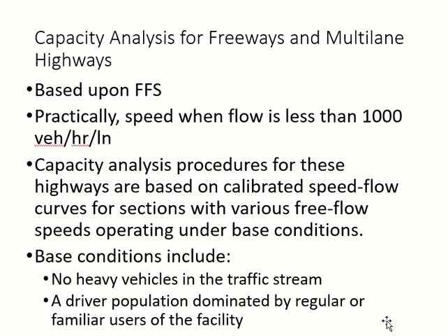For both cases we have base conditions, meaning ideal conditions, which include that there are no heavy vehicles in the traffic stream. Obviously we don't expect this to happen in the peak hour, but ideally our analysis is based on the assumption that we don't have any heavy vehicles in traffic and all the drivers are familiar drivers.